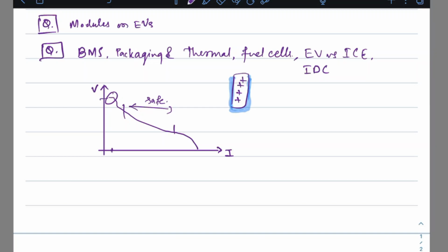And which particular branch, right? If you have a large EV battery, it will have multiple cells connected in series and parallel. Cells connected in series make a branch. Branches connected in parallel make the battery pack. So which branch you charge will also determine how fast you can charge. It would depend on how cleverly you design your algorithms while clearly knowing your optimal trade-offs.